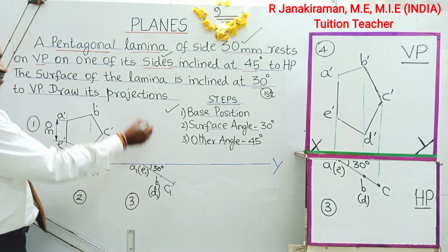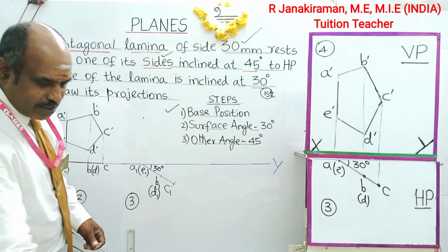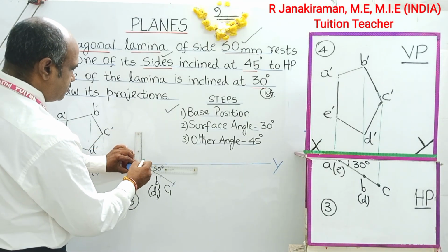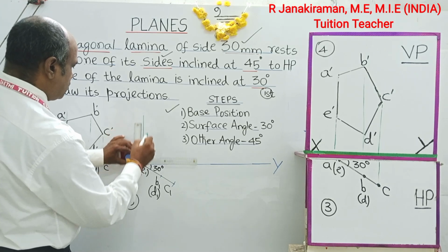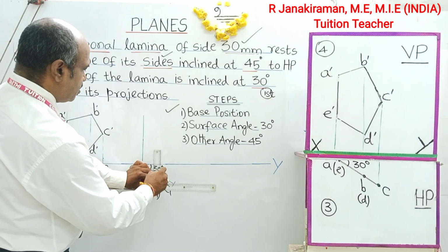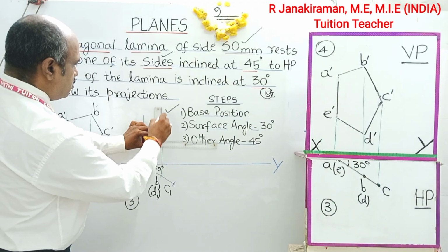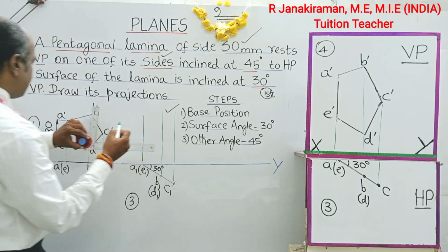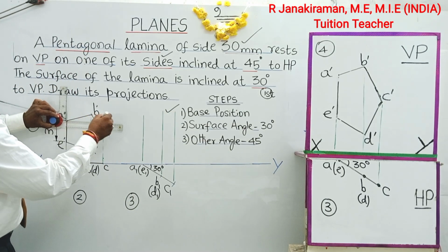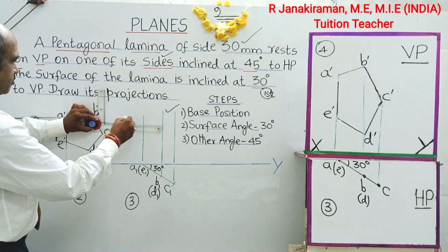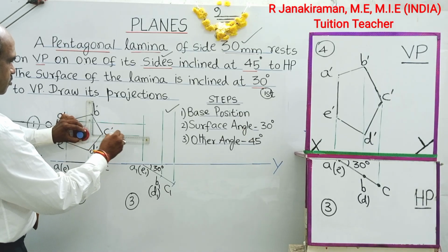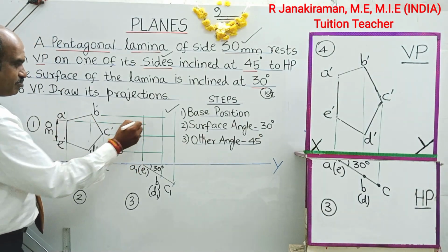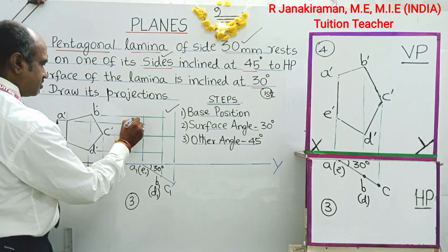Next we go for the corresponding front view. So take a 2H pencil and draw vertical projectors from various points. Then draw horizontal projectors from the previous front view. Vertical A and horizontal A intersect here. This point shall be marked as A suffix 1.